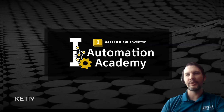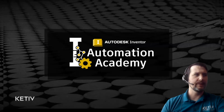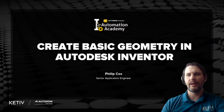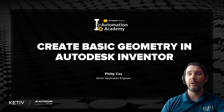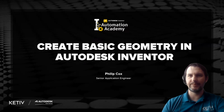In this video, we're going to be expanding on some topics that we focused on in a previous video, where we set up an Inventor add-in. In this video, we are going to be expanding on that by creating basic geometry in Autodesk Inventor. In doing that, we're going to be creating a WinForm and populating it with various buttons and fields and labels, and then showing how you can trigger off those buttons to make basic geometry, in this case, an extrude, based on the inputs given. So without further ado, we'll just jump right in.